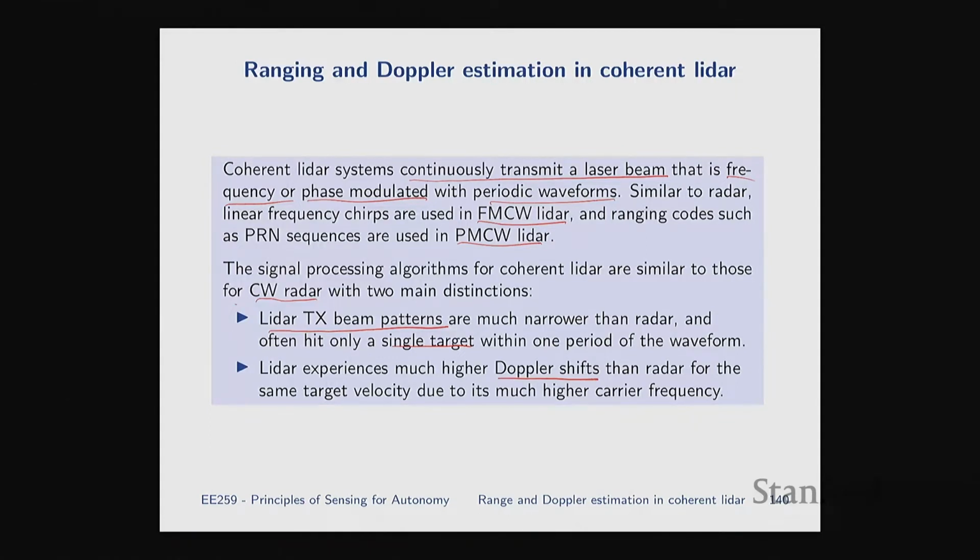And if you remember, for instance, when we were developing radar DSP, FMCW radar DSP, we used the fact that Doppler shifts were small. Specifically, we assumed that within one chirp time, we can ignore Doppler shift because it's much smaller than the frequency shift that is induced by just the range effect, and we kind of baked that assumption into our DSP development for radar. Now that doesn't hold for LiDAR, and we'll see today how we should handle that.